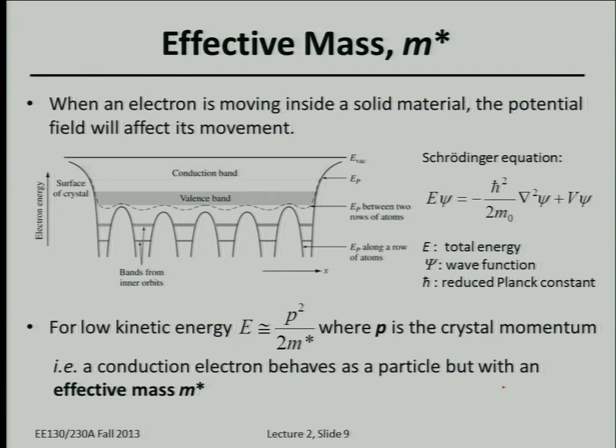If there's lots of spacing between atoms, it's easier for an electron to move. If the atoms are really tightly spaced together, it can actually end up being more difficult for an electron to move in a crystal. So it really depends on the crystalline direction, whether or not you're distorting the crystal, and so on. But in most integrated circuit devices, yes, we take advantage. We orient the transistors to take advantage of the directions that have the lower effective mass.